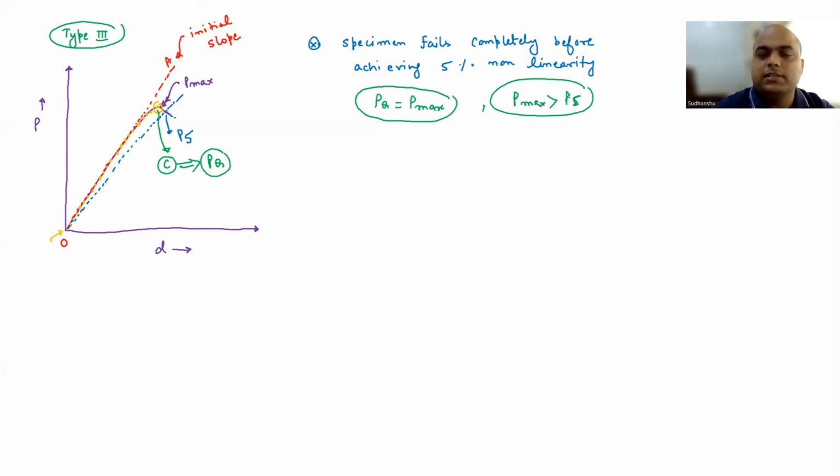Okay. So now we have discussed the three types of curves given in the ASTM standard. We can calculate the PQ value now. This PQ will be used to calculate the provisional fracture toughness. And you know what provisional means, right? It is like your degree. Unless you satisfy all the degree requirements, you get a provisional degree certificate. Same thing here. Unless you satisfy a few criteria for fracture toughness to be called plane strain fracture toughness, we will have the value of KQ, which will correspond to the load value of PQ. And once the criteria are satisfied, KQ will become equal to K1C.